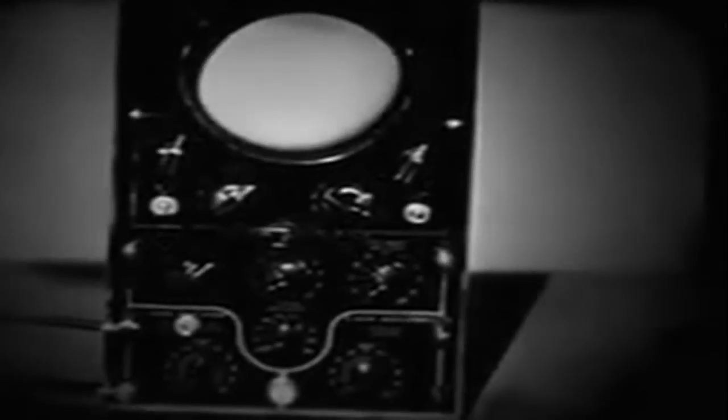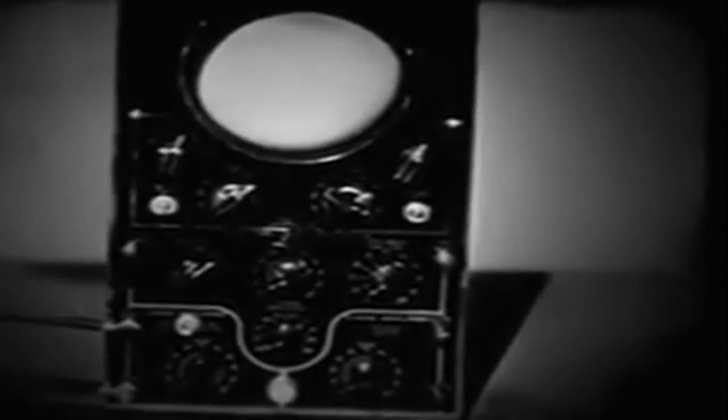The exact frequency desired can be obtained by using the fine frequency control. To study its characteristic patterns, a 400 cycle source is connected to the vertical amplifier. We turn on the beam, adjust intensity, and focus to get a sharp spot. Not too bright. Then, properly center the spot.